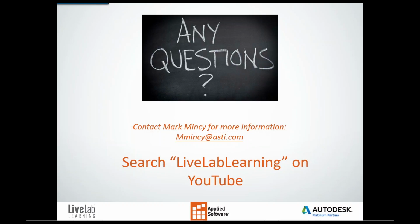And I'll give you a little tip. When you go there, there's a little button on the top right-hand side that defaults to the United States. If you change it over to Europe, you'll have 3 times the amount of information, or different information and content that you can look at. The fact that it brings it in metric doesn't matter, because if you're used to Revit, you know that you can bring in Revit content, and if you're working in Imperial, it automatically switches it over to Imperial.